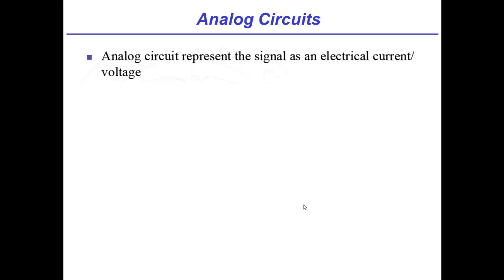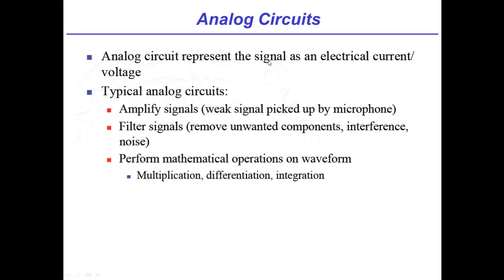So, okay, now I want to discuss this distinction between analog and digital circuits, because it's something you hear a lot, particularly if you're going to become an electrical engineer. You're going to hear a lot about this. So an analog circuit really is interested in representing some signal of interest, either by the electrical current or voltage, and attempts to deal with most of that signal, okay? And you'll see what I mean when I contrast it to digital.